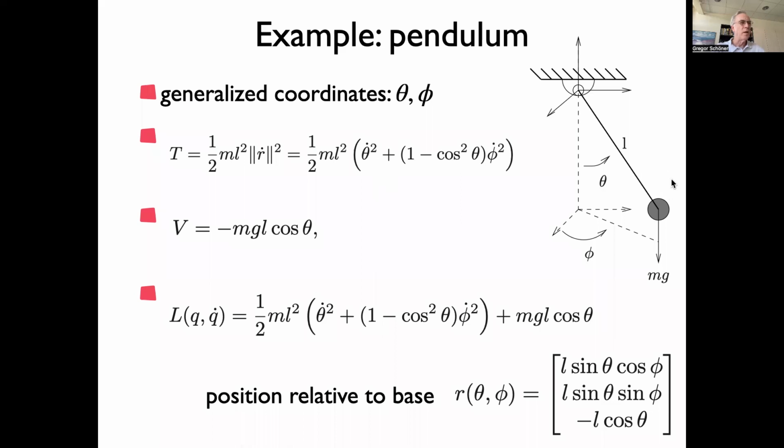If you have some velocity theta dot, then the velocity of this element in outer space would be proportional to the length, and along this it would be really just theta dot. So the linear velocity would be L times theta dot, and then in this plane you would have to look at the effective radius, right?